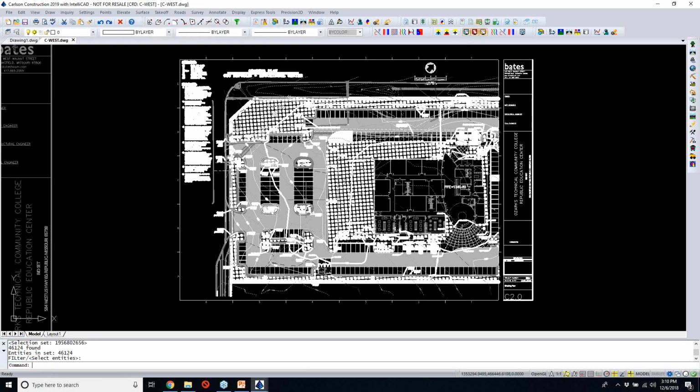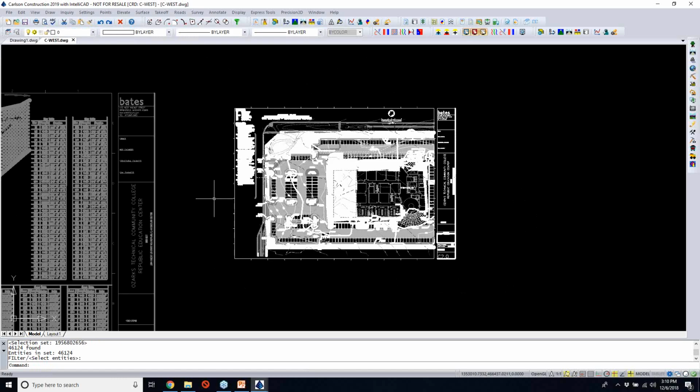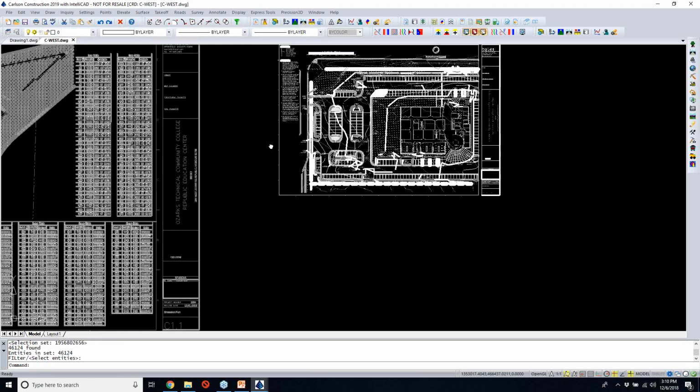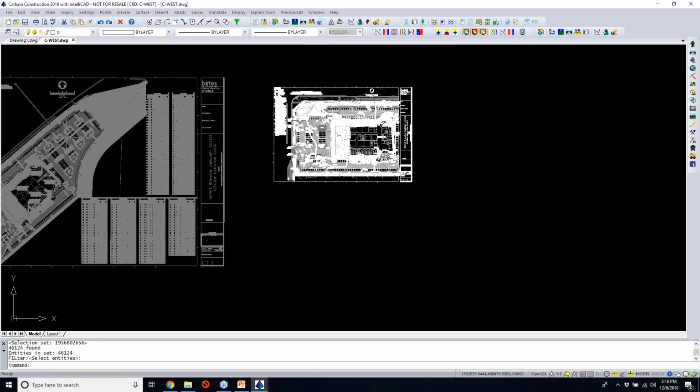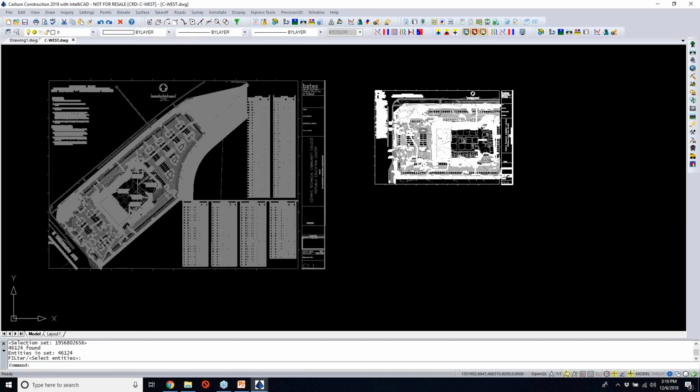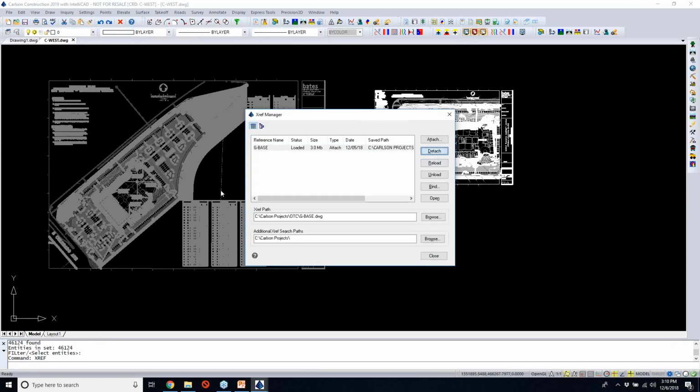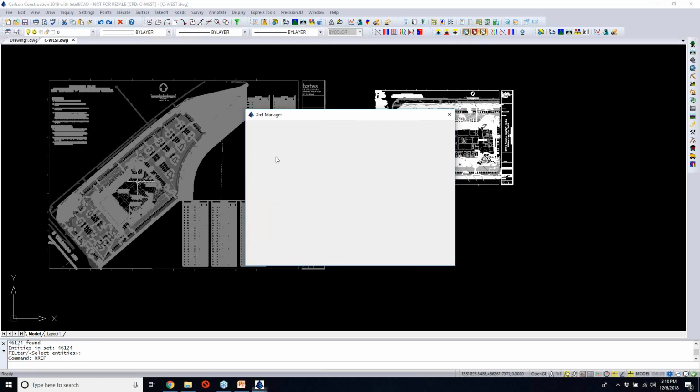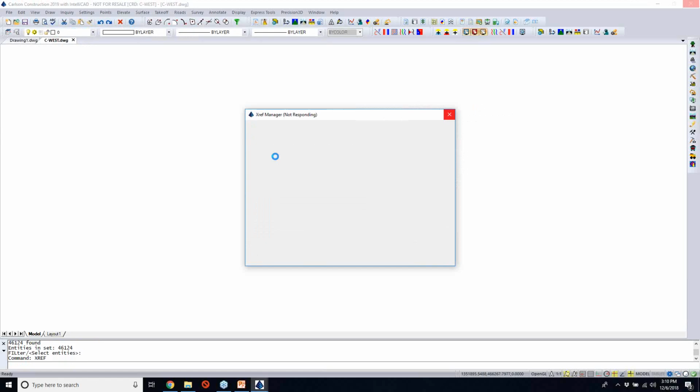So with that, what I'm going to do is create a brand new layer. And actually, I guess what I can do right now is unload, or actually I can probably just detach for now this external reference. So again, with my old DOS skills here, I'm just going to go ahead and detach the external reference just because I don't need that getting in the way. And I'm going to issue my save command because, again, these are things that I just get in the habit of doing.